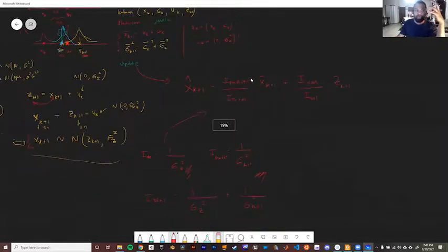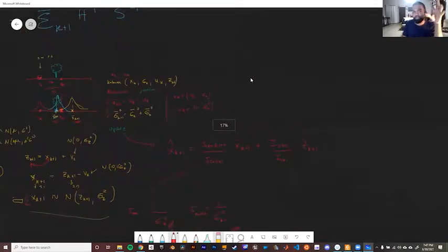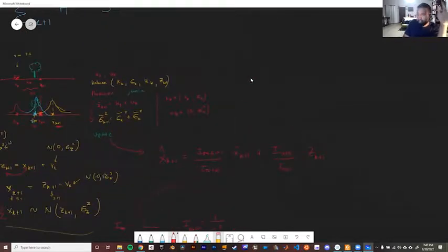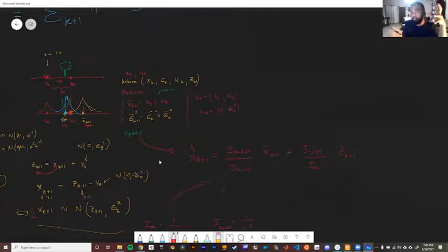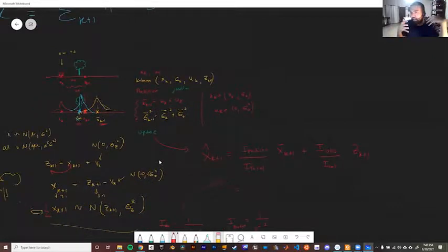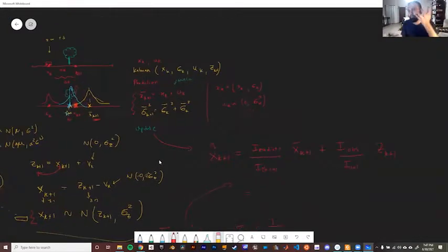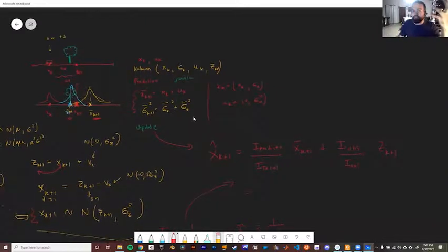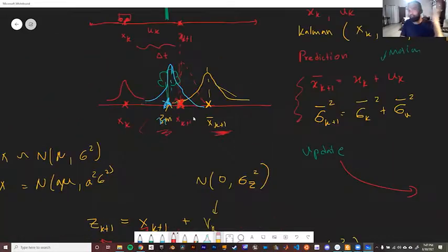All right, so what I want you all to remember with the Kalman filter is there are two steps here. One is the prediction, which is with the motion model. It's predicting how much uncertainty the motion is going to provide. And then it takes an observation and looks at how much uncertainty is there in the observation, and then finds a weighted combination of the two. And then hopefully the combination of the two will be a better answer than if you would take one at a time, right? So in most cases, that's the case, right?